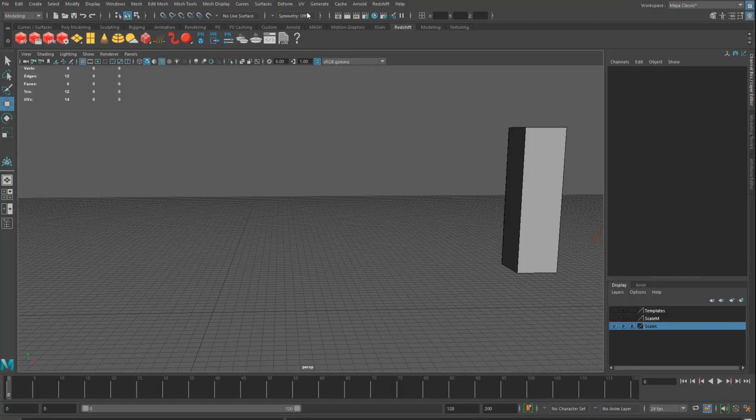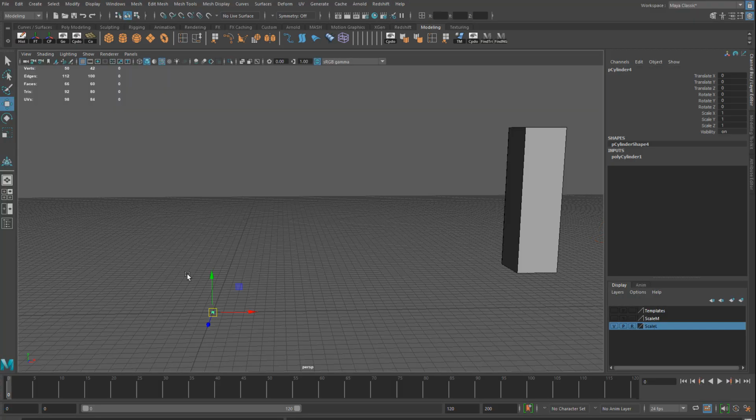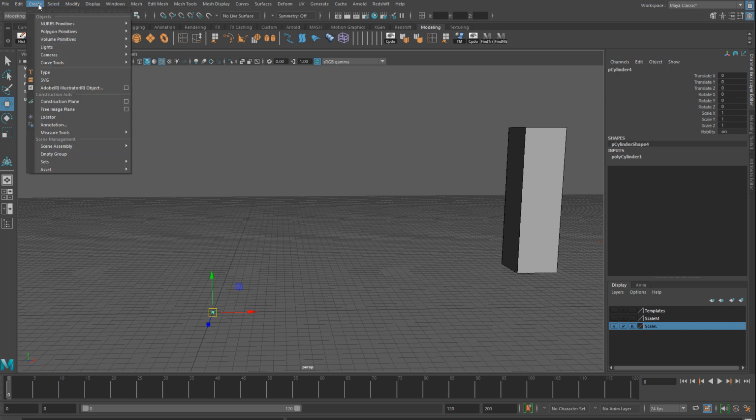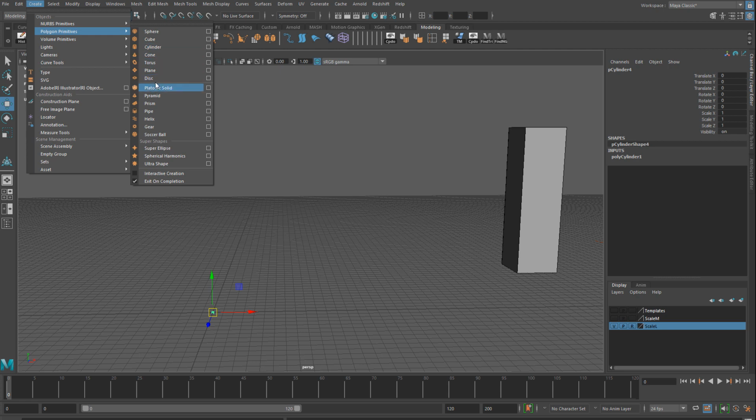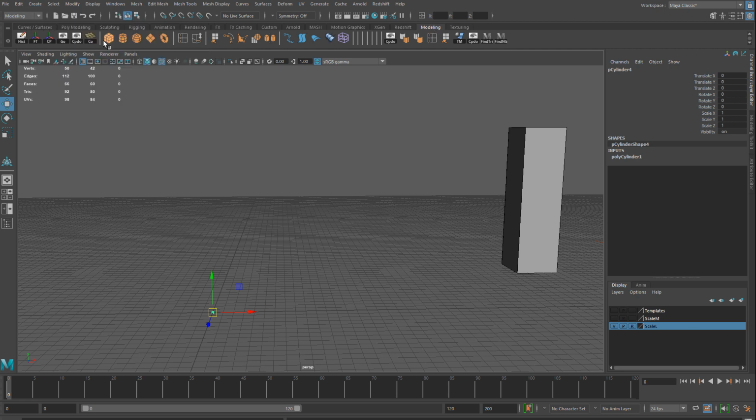So let's start with a cylinder. And I already have my primitive shapes that I use, the polygonal primitive shapes, on my tool shelf. So that's what I'm going to use. Most of these are found in Create Polygon Primitives, and they're right here. It's just quick access for me to the most common shapes that I use. So I've created this cylinder, and let's go into the Input tab, and I'm going to set radius to 34. Radius is half the size of the width of the barrel that we saw the dimensions for. So this is in centimeters. So obviously 68 would be too much, and radius is half of that. So 34. And then height, it is 93.